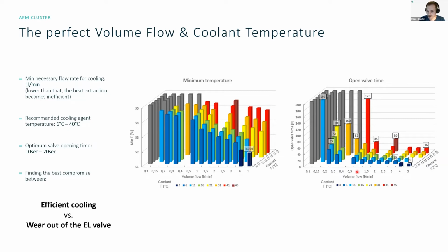And even if we have a 1 liter flow rate, these 35 seconds are quite long. The thing is, we are using a normally closed valve, so it consumes energy as long as it's open. And so shorter opening times are also more efficient. That means if we're more in these yellow or greenish bars, then we are in the perfect range. So we have an optimum valve opening time of 10 to 20 seconds.